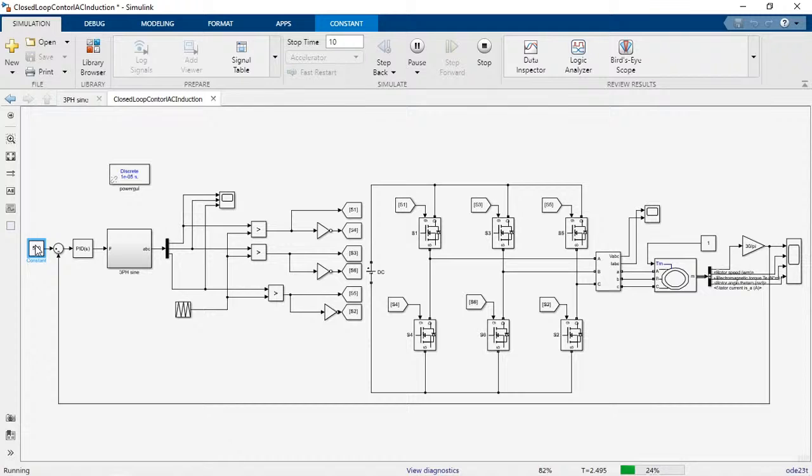You have to remove all the SimPowerSystem blocks, and here you can straight away keep it as input for the Arduino controller. By adding this entire thing, it will work. You have to remove all the additional components for hardware code simulation.